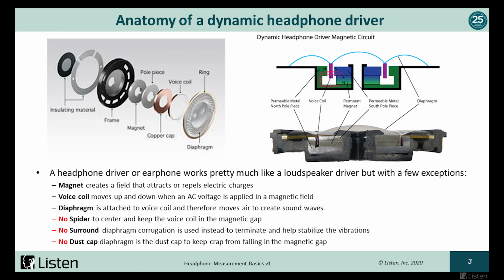And if you're not careful, if you get a wrinkle or a little crease in the diaphragm, you can create a buckling motion and get a sharp snap. So that's one of the defects that you've got to be careful of when you're creating the earphone driver diaphragm. I've been able to pick that up on a production line with loose particle detection.